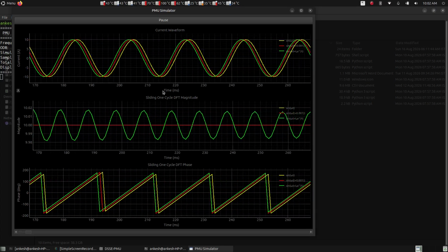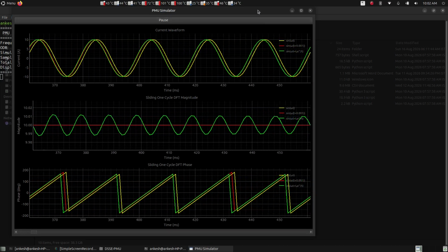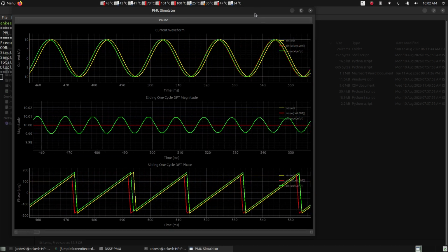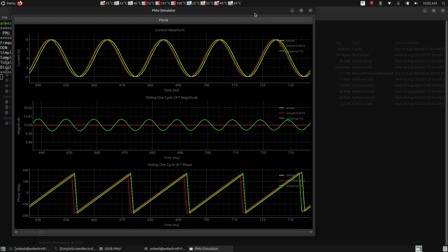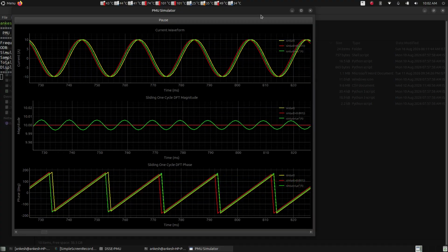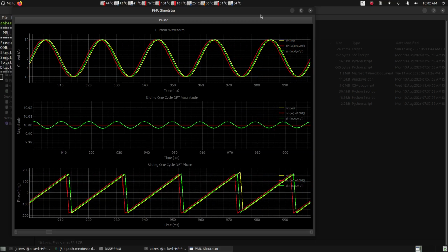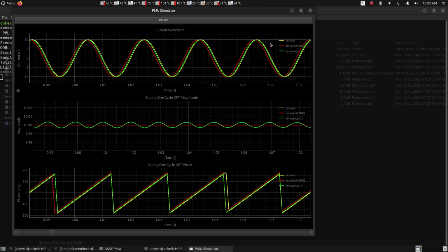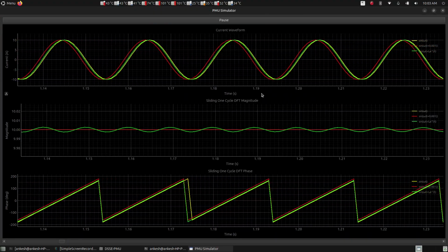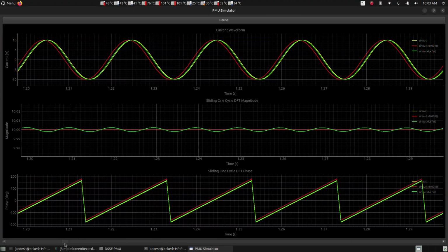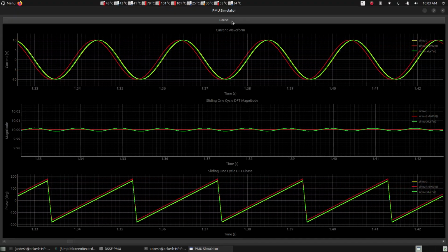So this is the waveform which comes in the output. This particular PMU simulator has 3 waveforms in output. It has a simple sinusoid wave output which is Im sin omega t, then we have Im sin(omega t plus phi), and then we have Im sin omega t plus e raised to the power minus t by tau. So these 3, which is a DC decaying component in the third section, and we can see the function of this DC decaying function which we added to the sine wave in this plot itself.